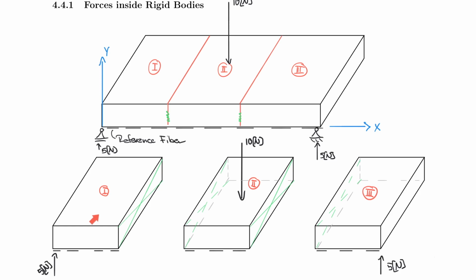Okay, so now we can ask ourselves, how do I bring this piece, element number 1, back into equilibrium so that it doesn't fall down here on the glued line, because it didn't fall down up here. I just virtually cut the system and pretend that I'm analyzing the glue now. So what do I have to do? Of course, you already see that it's in imbalance in the vertical direction. Therefore, I need to somehow bring a force into the system that pushes against the 5. I don't really care about the values here, but I care that I need to balance the vertical direction.